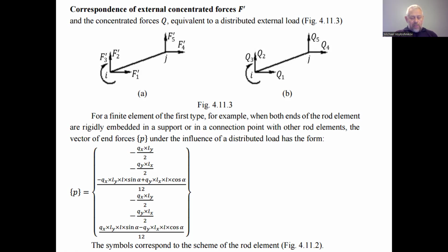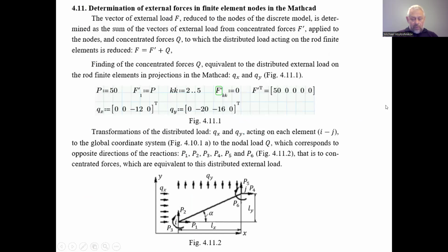The first force is the projection of the end forces of the finite element on the axes, caused by the distributed load. These are the external forces. This is the scheme we have in our definite issue, but this is a scheme for any general approach.